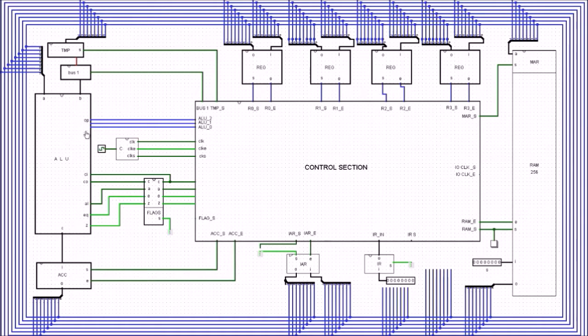But in order to do that, we have to have gone through an ALU instruction. So at a particular point of an ALU instruction, one of these would potentially go high. Now after the ALU instruction is complete, we want to do the JUMPIF instruction. But that means that the information that was here previously will now have passed on, and it would have gone out of the accumulator.